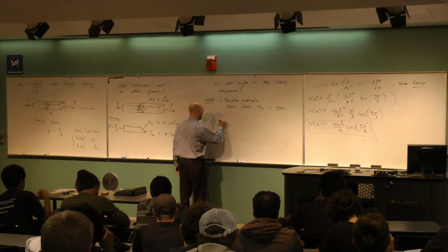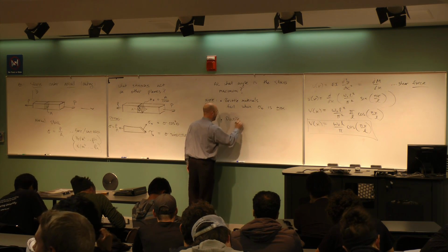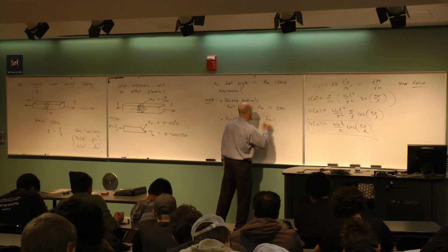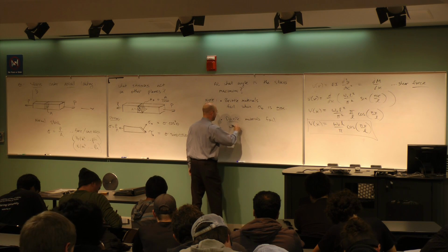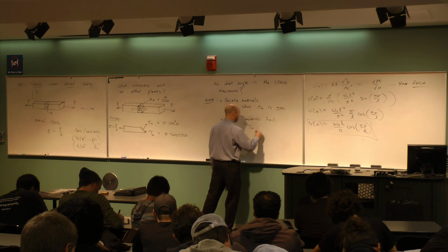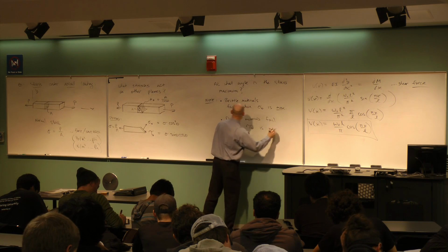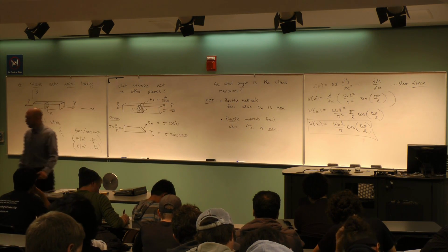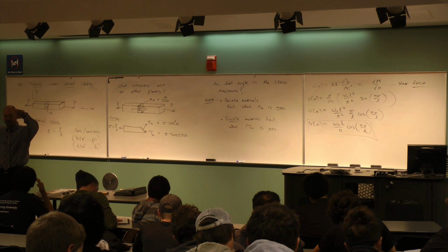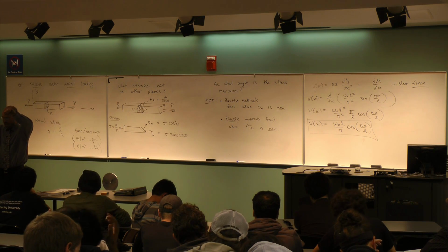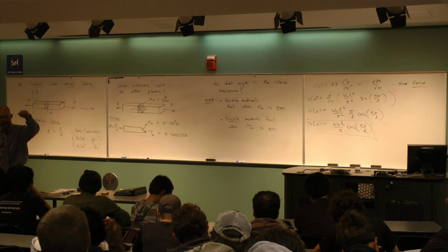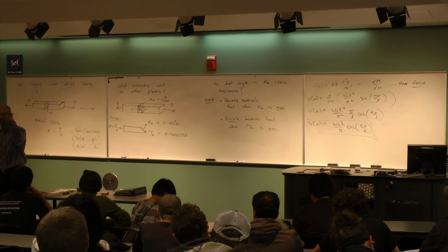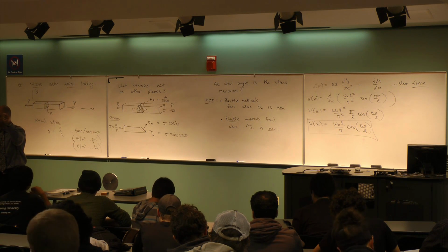So this is point one. Okay, ductile materials, these guys fail where it turns out that the tau theta is max. Okay, and so what do I mean by a ductile material? A ductile material is a material that when I load it past its elastic limit, I can now bend it, like a paper clip. I can take a paper clip and I can just bend it, and now I have a bent paper clip, right? I don't have two pieces.